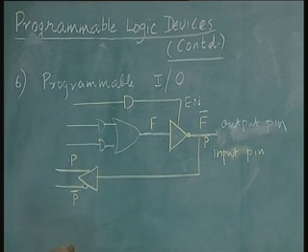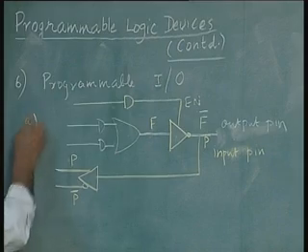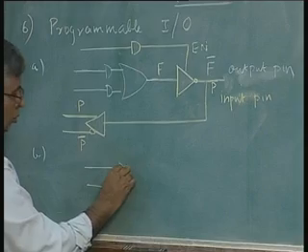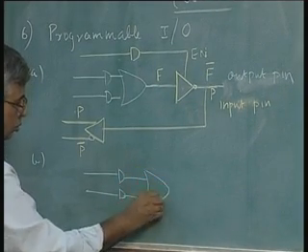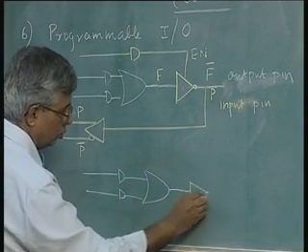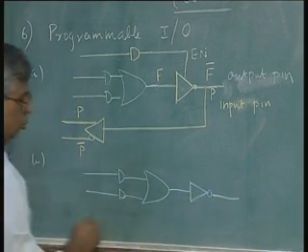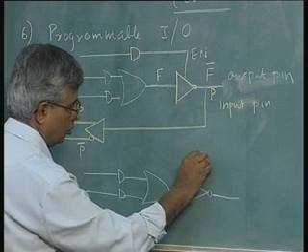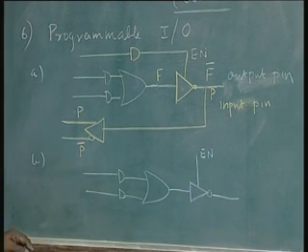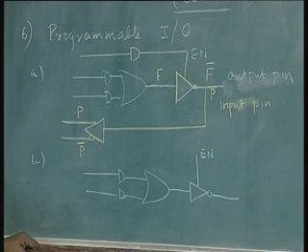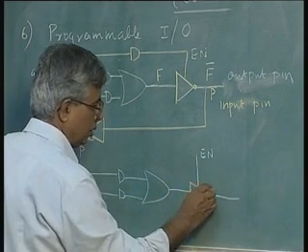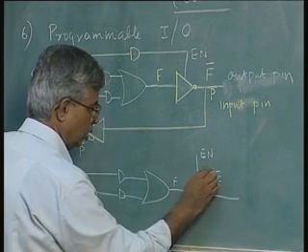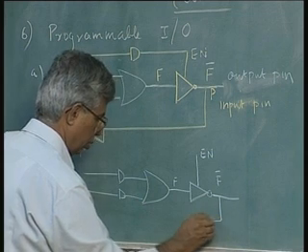So, this can also be simplified to another variation where this can be an extra pin in your drawing, whereas I can enable this by this. If enable is 1, this output is connected to this. If enable is 0, this is connected as an input.